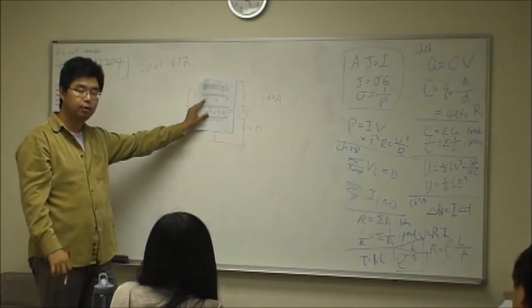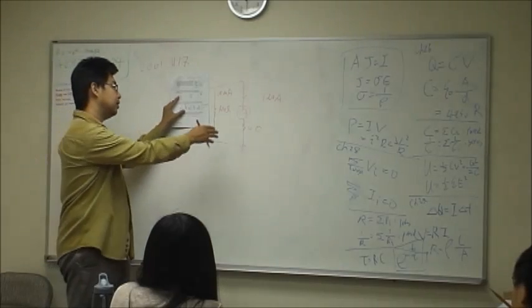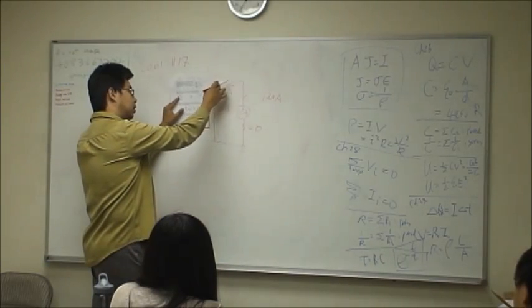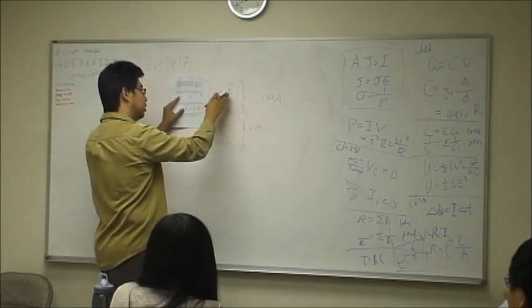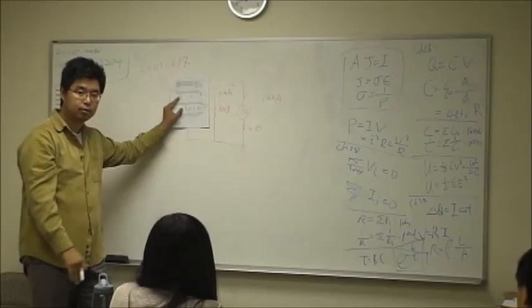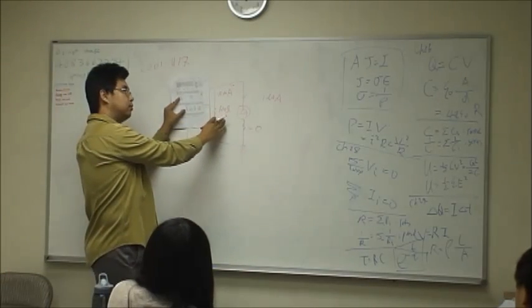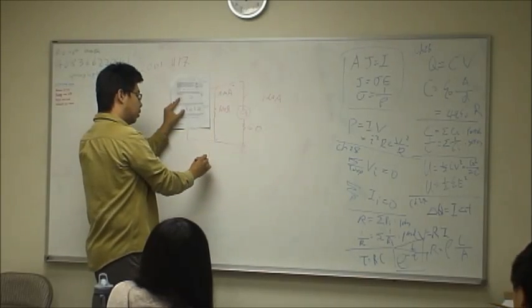Means that, for example, I just need 1 microamp, 10⁻⁶, to go through the ampere meter and it's working well enough. So what happens is that I put another resistance beside it so that the majority of the current goes through this path, and just 1 microamp goes through here. Okay? So when it's 10 milliamp with 100 ohm, I can calculate the difference here is about 1 watt.